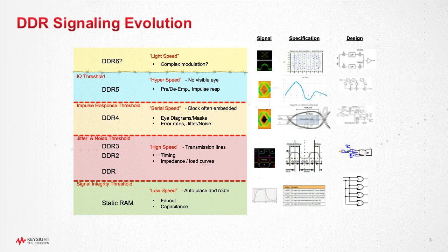But the way that you need to think about the signaling at the end is with the eye diagram itself and the concept called an eye mask, which is not one-dimensional like setup and hold, but it's two-dimensional because it deals with voltage and timing issues. And the big thing here that threw people for a loop in many cases was that it became a statistical spec.